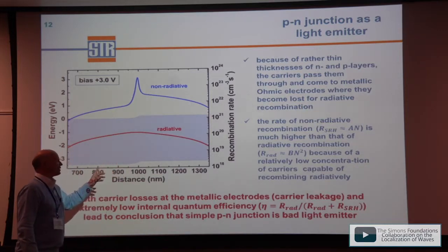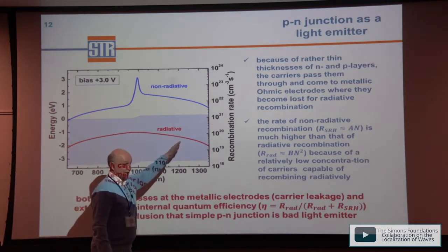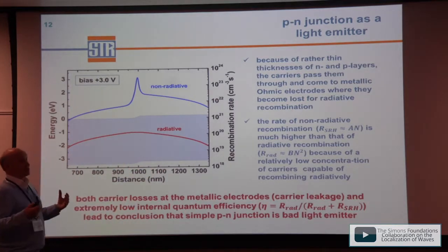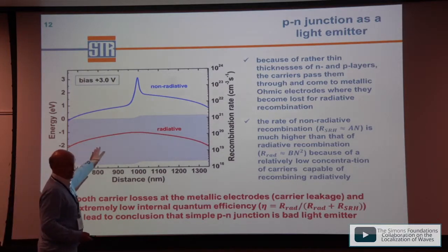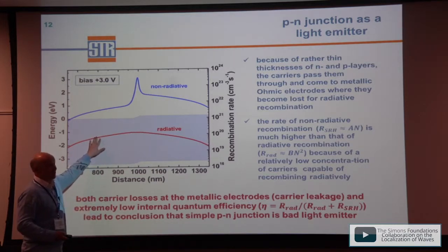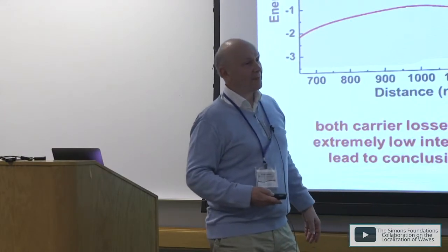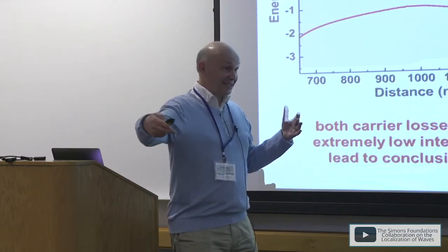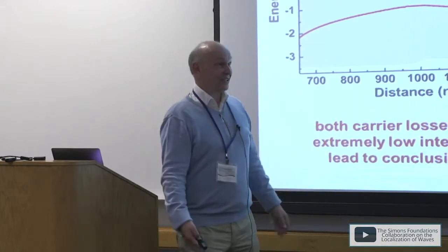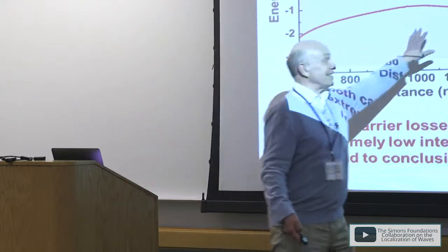The total current includes, first of all, the leakage, which is related to the carriers that are not recombined in the structure. This occurs only if the structure is thin enough. If the structure is thin, the leakage is small, but nevertheless the radiative recombination rate will be low. But it depends on the thickness of the structure. If the thickness exceeds the diffusion length, there is no leakage. In a thick pin junction, you cannot see a leakage. All the carriers can be recombined.